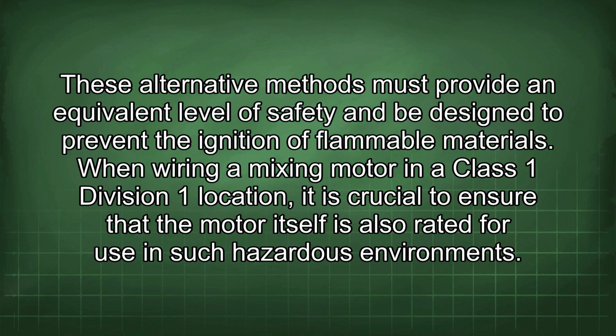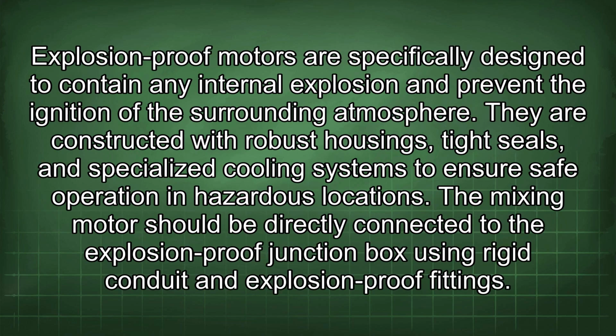When wiring a mixing motor in a Class 1 Division 1 location, it is crucial to ensure that the motor itself is also rated for use in such hazardous environments. Explosion-proof motors are specifically designed to contain any internal explosion and prevent the ignition of the surrounding atmosphere. They are constructed with robust housings, tight seals, and specialized cooling systems to ensure safe operation in hazardous locations.